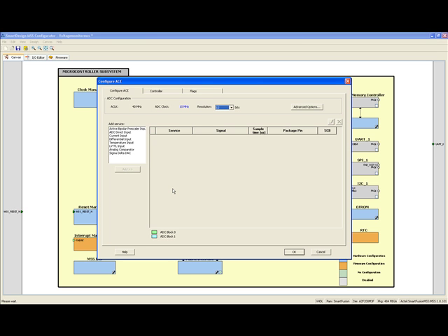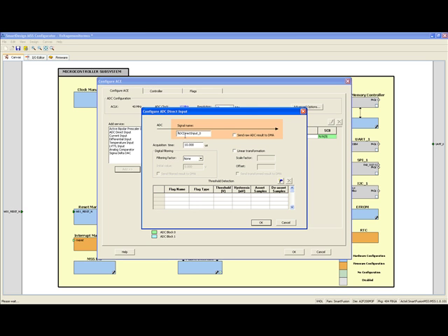This design uses the TM0 input pin of the SmartFusion FPGA. TM0 drives the signal conditioning block 0 analog to digital converter input. TM0 is connected to the potentiometer of the SmartFusion evaluation board, which will be used to vary the voltage monitored by the SmartFusion device. On the Configure ACE dialog, select the ADC direct input and click Add in the Add Service window. Leave all other default settings and click OK.